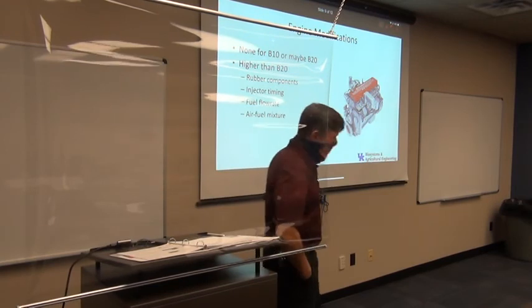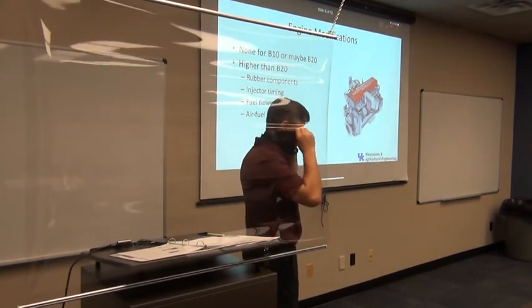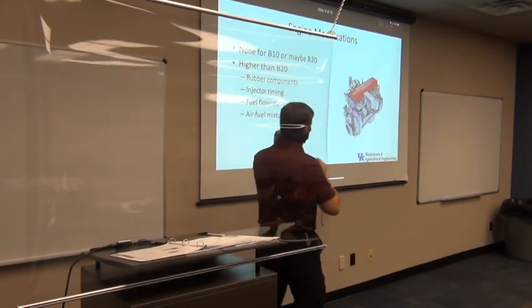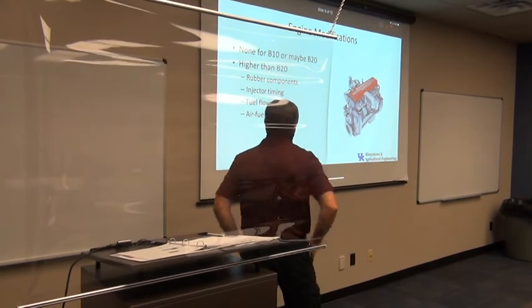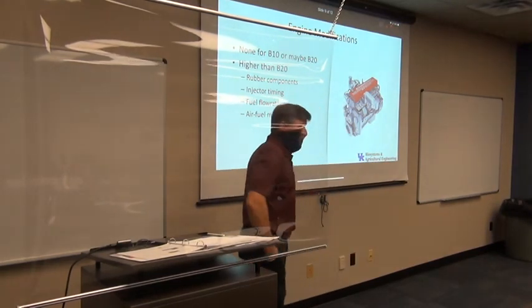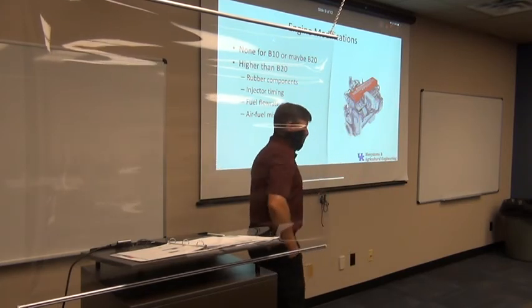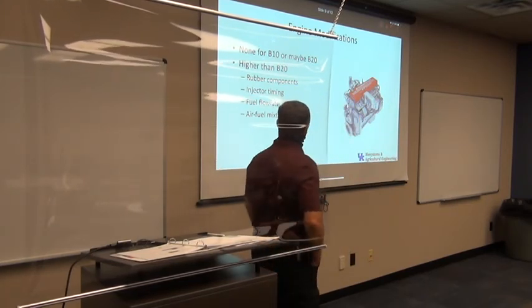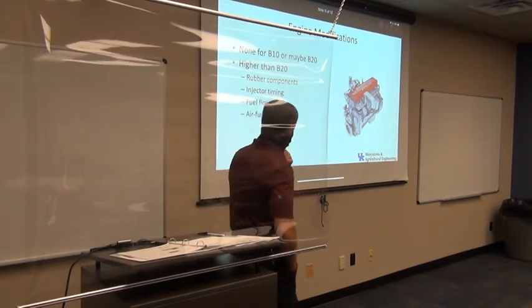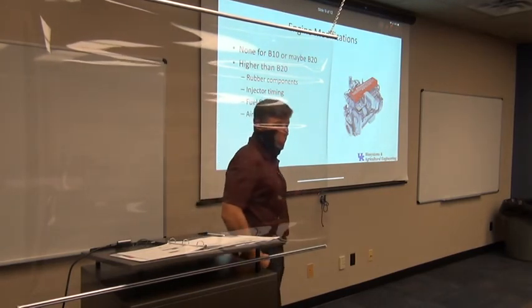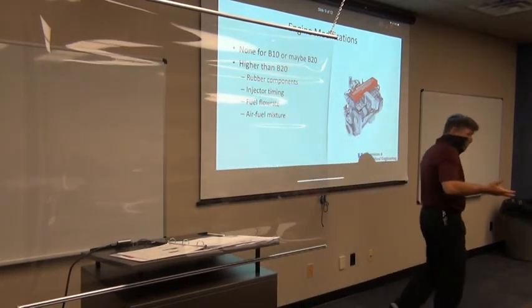Again, this was an extension presentation I put together for farmers when they started selling all this biodiesel, and farmers were like, oh my goodness, it's going to kill my tractor. What's going to happen to it? Do I need to modify my engine? This is going back to spark ignition stuff for biodiesel. They're worried, do I have to do anything to burn this B20 that's coming in? No. Anything up to B20, nothing. But if I get above B20, above 20%, here's the deal. And ethanol is kind of the same way.